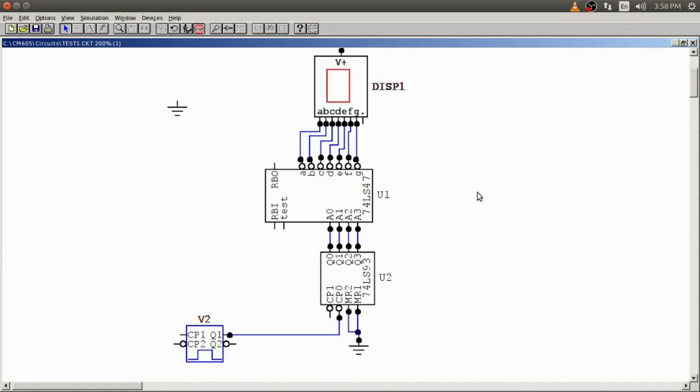So why is it happening? It's a 4-bit counter. It is supposed to count from 0 to 15, but now it is counting only 0 to 1. As we have mentioned, though it is a 4-bit counter, internally this Q0 is a separate flip-flop, and Q1, Q2, Q3 are another 3-bit counter. So I need to explicitly connect the clock of this 3-bit counter to the first one, otherwise they remain isolated. CP1 is actually the clock for this 3-bit counter.